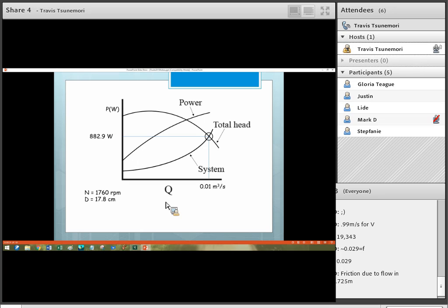Performance of centrifugal pumps while pumping water is used as a standard for comparing pumps. So if no fluid is given in the problem, you can assume it's water, because that's the reference fluid. And if we want to compare pumps at any other speed than that at which the tests were conducted to get the pump performance curves, or to compare performance curves for geometrically similar pumps, so different diameters, we're going to use the affinity laws.